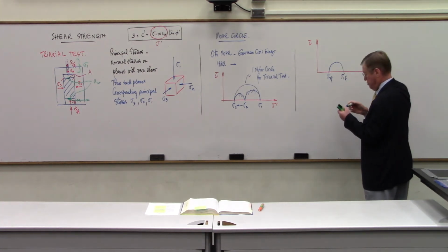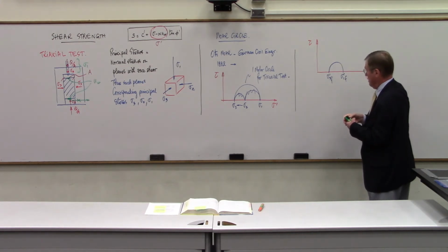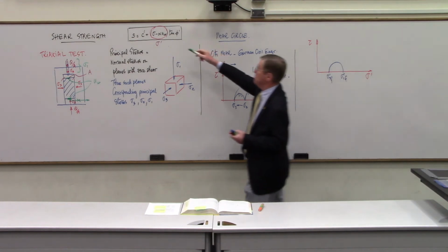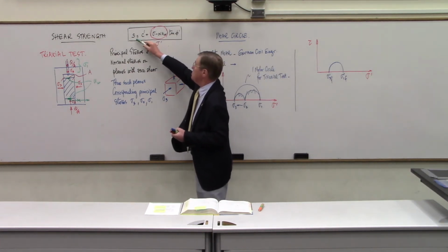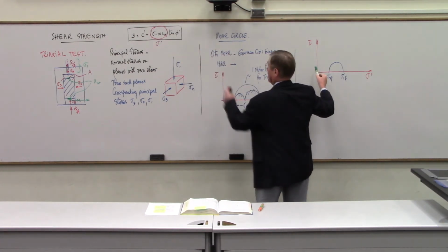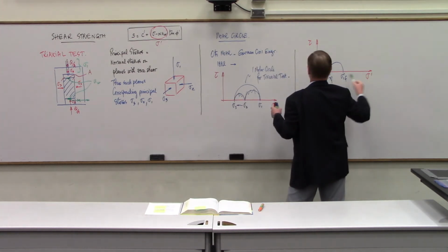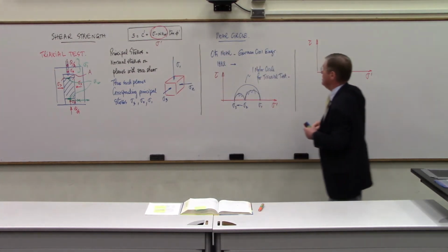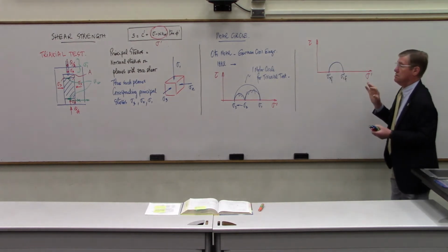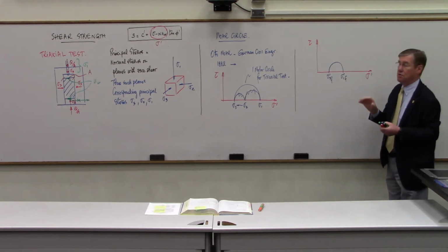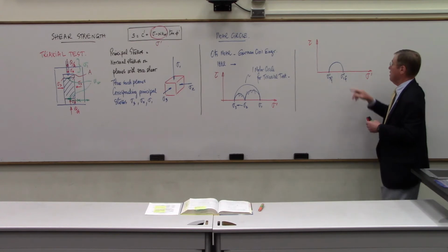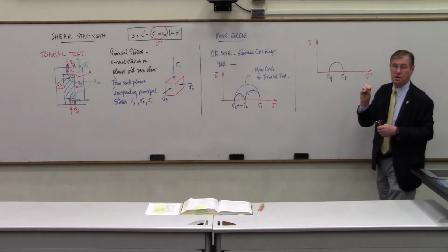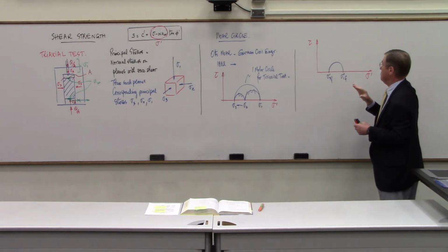And then you know that there is an envelope, which is this expression right here. S is a shear stress, and sigma prime is this. So this is a straight line, as I mentioned last time, and that straight line is defining the failure envelope. This is a circle that represents the state of stress of the sample at failure.